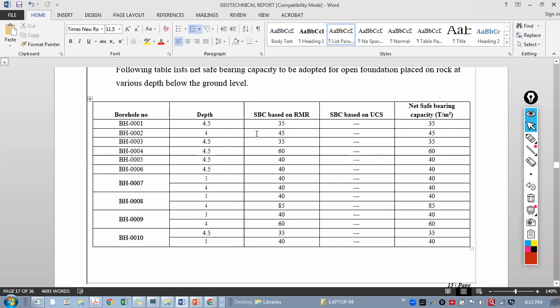Okay. As you are giving the suggestion, I will go for 40 tons per meter square and 4 meters, which is, we can say, value engineering thinking, so that you want to save the cost. You don't want to apply these values to all the area. That can be possible, fine, but it depends on the experience.